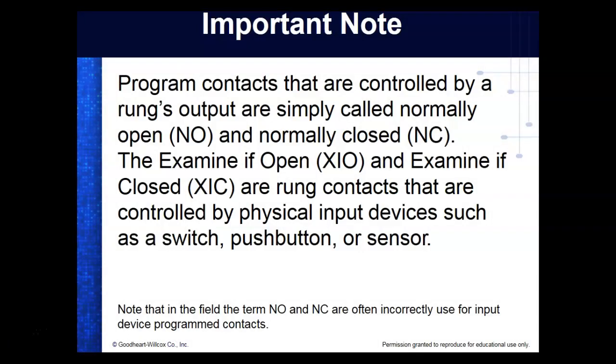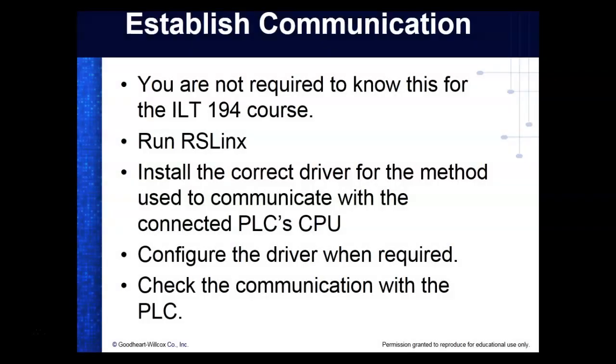So program contacts that are controlled by a rung's output are simply called normally open, normally closed. Examine if open and examine if closed instructions are contacts that are controlled by physical input devices such as switches, push buttons, and sensors.